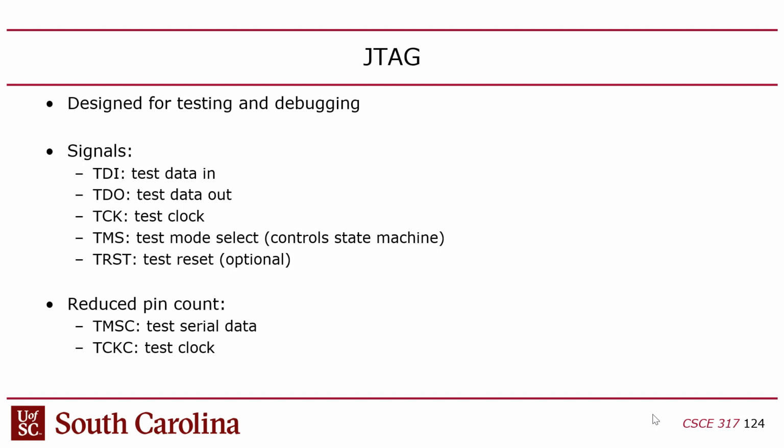So the only way to tell if this thing is on is if you have the ability to test every pin somehow. And that's what JTAG was used for. JTAG was this thing where you would shift in bits for all of the pins, and then you could use that to test whether you had a good solder joint for these BGAs. But eventually they co-opted it. Now it's basically a side channel that allows you to get data in and out of a chip for a variety of reasons. In our case, mainly for debugging in console.